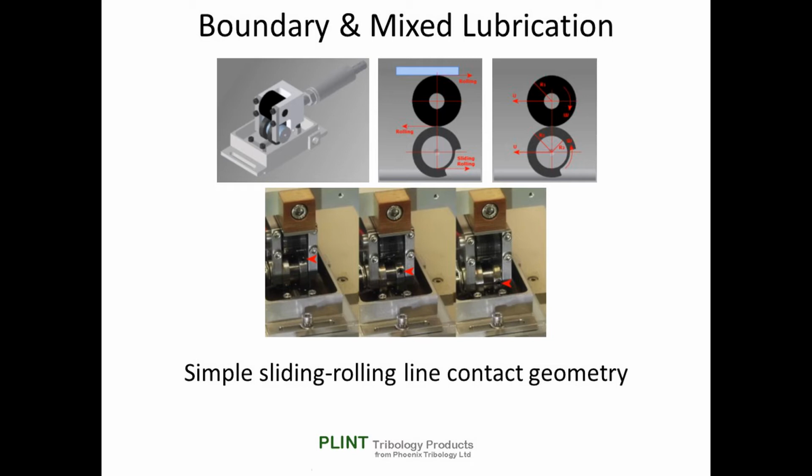The roller locates between two guide forks projecting down from a reciprocating head. The upper surface of the discs is in rolling contact with the needle roller cam follower, which is loaded from above via a loaded running plate. The resulting slide-roll ratio is determined by the diameter of the roller sample and of the discs.